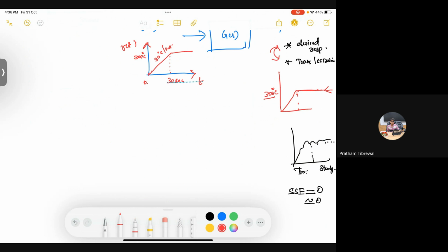So it will give a large tracking error when references change or if there is any poor disturbance rejection. So we go with a closed loop. We are going to introduce a controller, a proportional controller, which I'm considering for now for simplicity. We will see whether it is enough or whether we want to add some integral or derivative actions along with this.